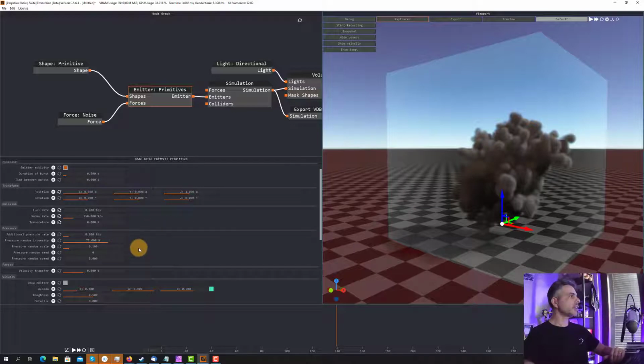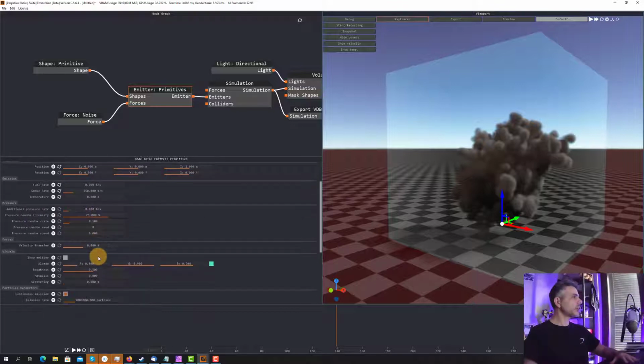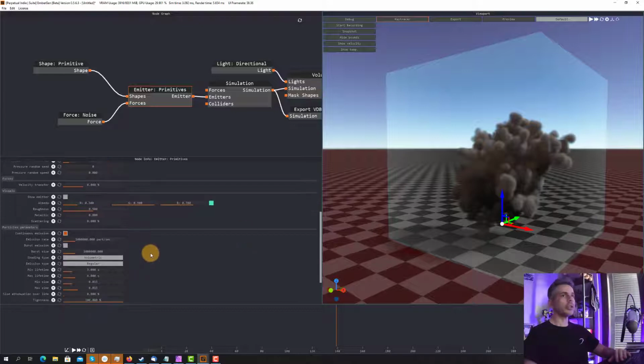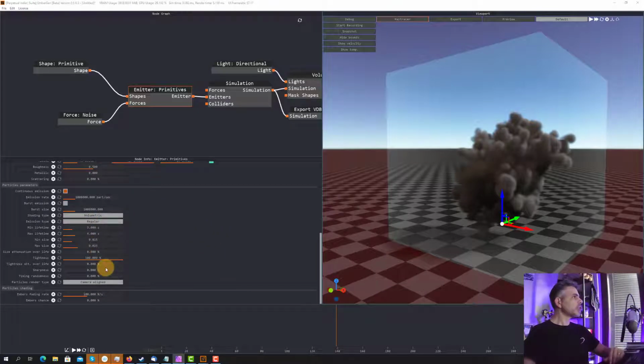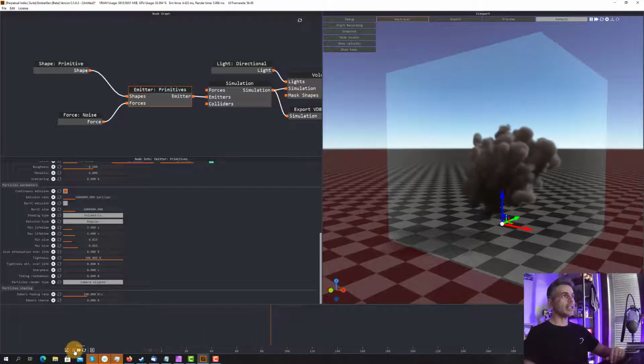Let's continue to check what we can do over the emission. We don't need to control the pressure because we have nothing so complex about the pressure because we have no explosion and stuff like that. Let's see, we have here the particle emissions, so maybe we can take care about also the emission animation. So we can decide when the cloud is emitted, because we are going to create a static cloud. So we'll emit the cloud, we'll see the evolution, and then we stop the simulation. That's the idea. So you see that we have the cloud evolution, and then we go to decide, for example, that we love a specific frame and we are going to use it as final.